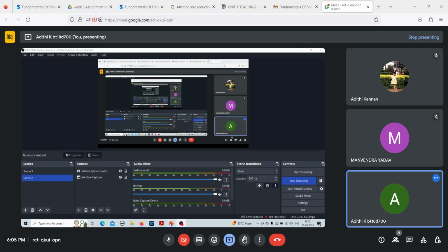Next in the column was surface diameter. You can also call surface diameter the number surface diameter. The definition is the diameter of a sphere that has the same surface area as that of the particle. If a particle has a surface area, say S1, then your sphere will also have the same surface area S1, and that sphere's diameter is known as the surface diameter or number surface diameter.